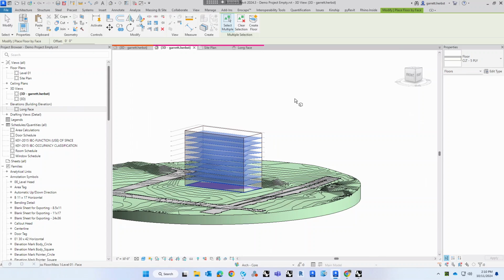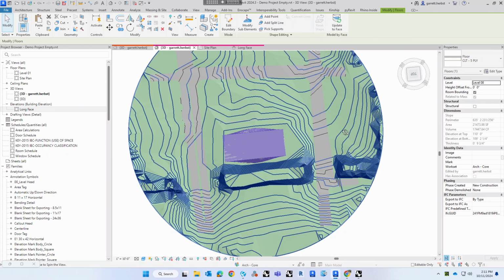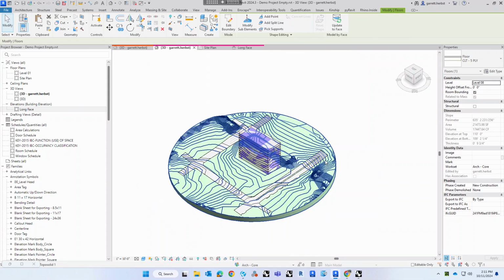So that's how to manually import geometry into Revit. Again, importing it into the conceptual mass is one of the unique ways that you can take Rhino geometry, import it, and actually be able to utilize it. Most of the other times, you're essentially just taking something that you can't model in Revit and just importing it into the Revit environment from a visual standpoint.